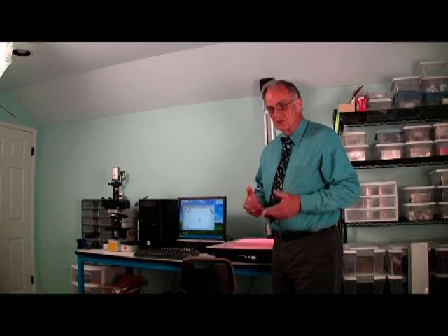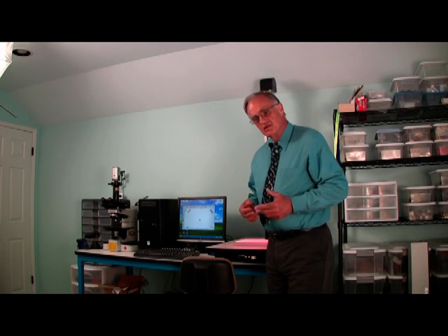Of course, you'll save these images for future reference. Now there's even a third way to verify the depth of field on a vision system, and that's in the event that the vision system is mounted to a robot or other mechanism. In that case, you can use the programmability of the robot to change the working distance of the camera throughout its depth of field range.